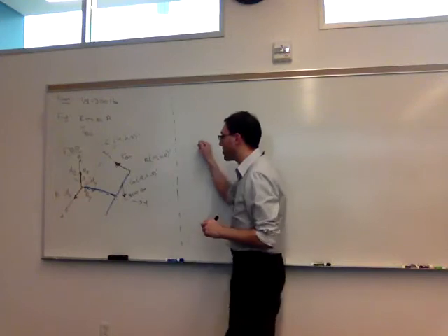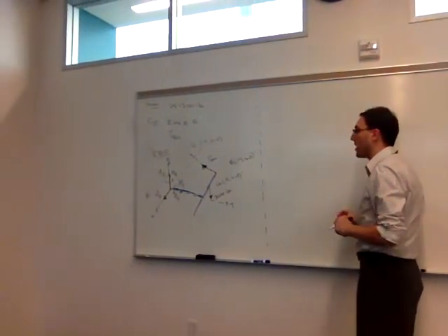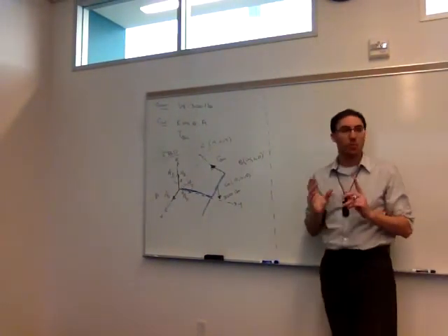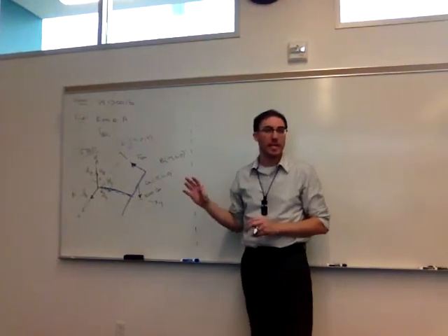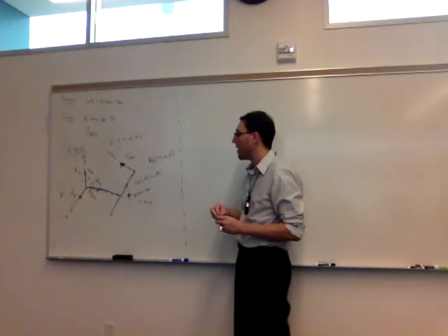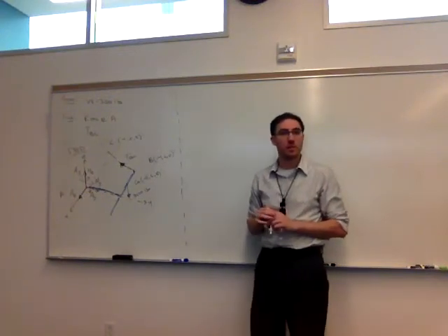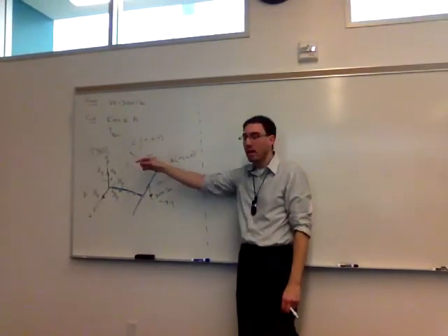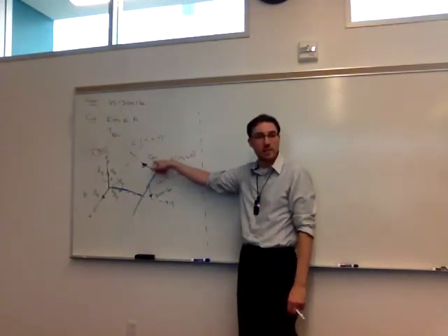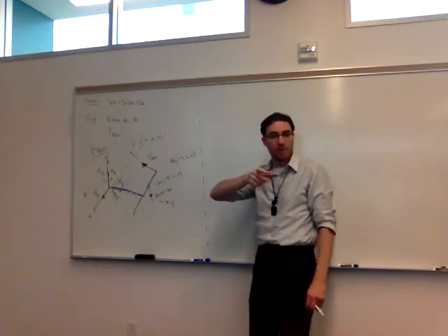All right, so now we can move on to, well, we'll get to the equilibrium equations in a second. We have to go back in our 3D mindset, and I recommend finding unit vectors we're going to need now. So looking at this, what unit vector are we going to need to solve this? Right, we need a unit vector that goes from B to C, because we know that we're going to have to express TBC in its component form.